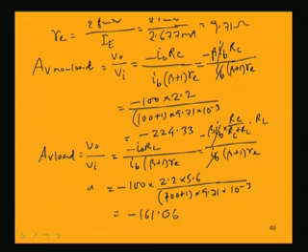So, now if we just see that when it is with load, the voltage gain reduces because of the fact that now the resistance RL, the load will be in parallel with RC. So, the equivalent resistance at the output will be reduced. That is why we are getting a lesser voltage gain than without load.